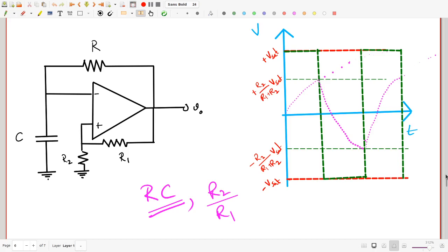Or of course, the last circuit that we saw was not even an input-output scenario. It had no input, it produces a square wave output on its own. But if you leave that one aside, all the other circuits we have seen so far do have an input and an output, but the input-output relationship is not a smooth one, not a linear one. So these are examples of what are called non-linear circuits. So the op-amp in these cases is not really working as an amplifier.